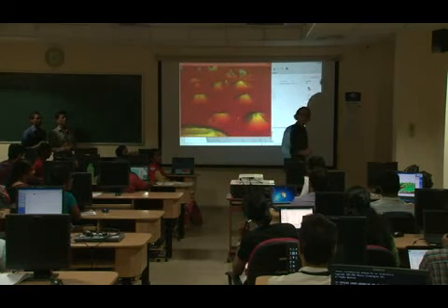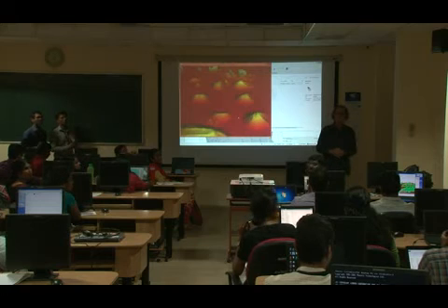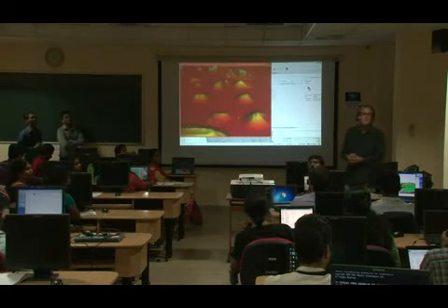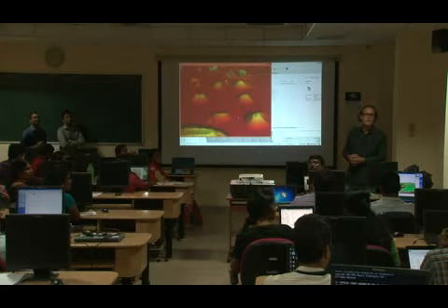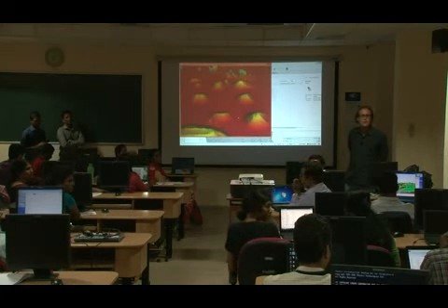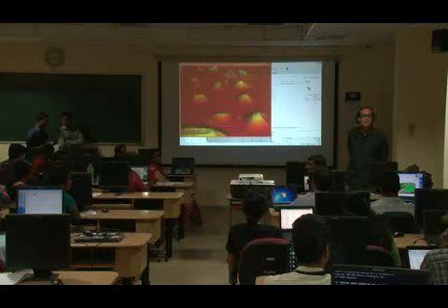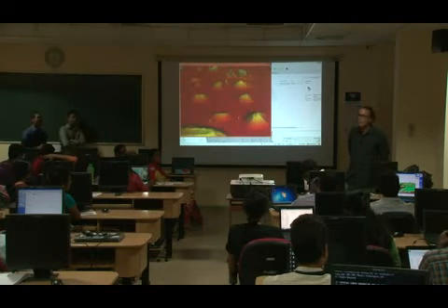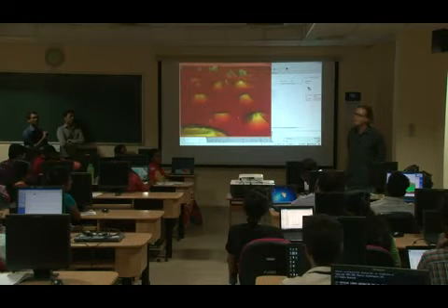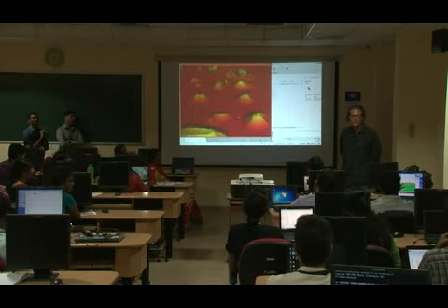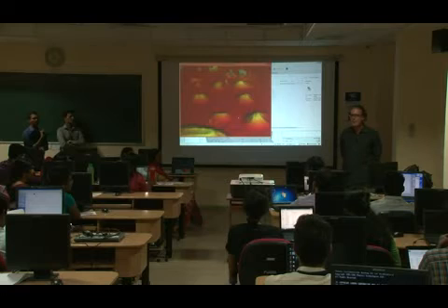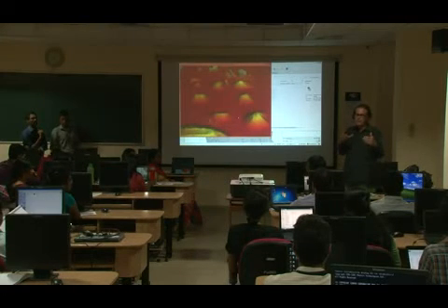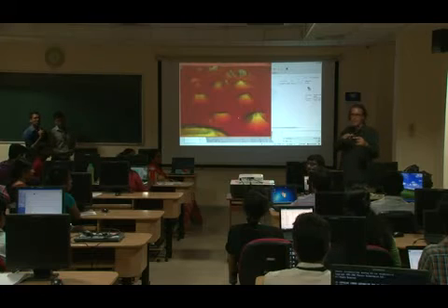I don't have one. Sir, if I am having 10 centimeter accuracy of the data, and I am automatically classifying these building points into shapefiles, how much accuracy will I get? Well, what I showed you today was more of a side effect of the modularity of LAStools, because lasboundary is not really meant to give you building edges. I just classify the points, and then I make a boundary around the points.